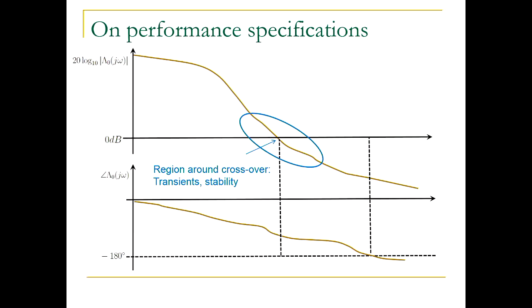Right, so you can see you did not encircle the critical point. If this phase is larger, you have encircled it, right? So for that special case, phase margin tells you first about stability, but also we saw it gives you a degree of robustness margin. How far are you from becoming unstable? Because what's phase margin? It's the angle you need to rotate the Nyquist plot so that it passes through the critical point, right?